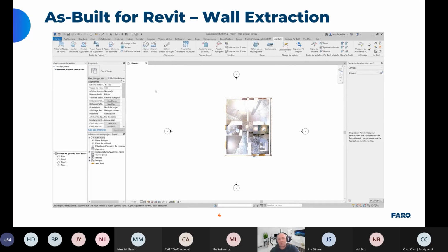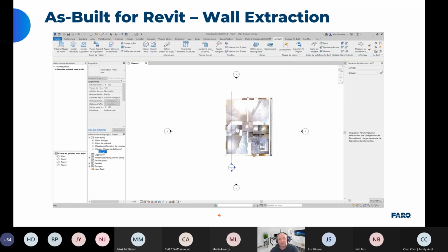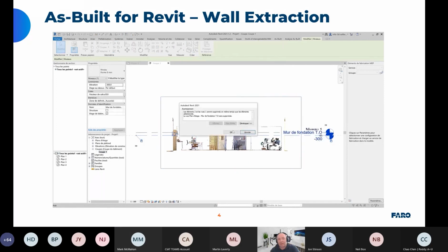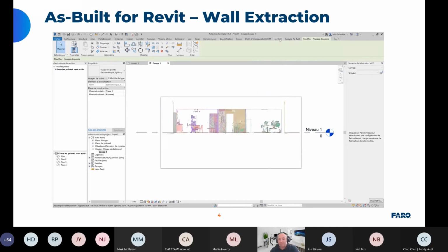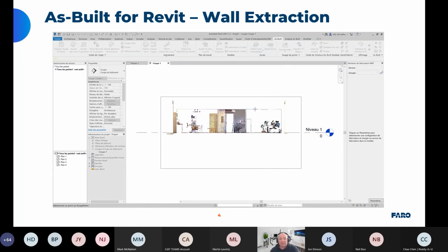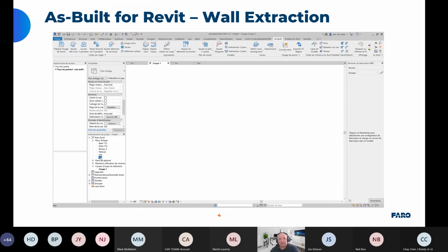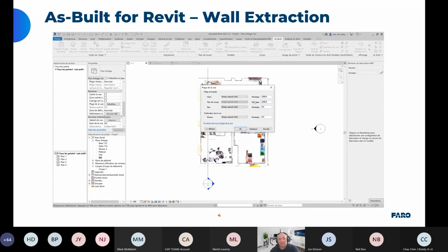After, we just select the views, so we remove the areas of point cloud we do not want, and once it's done, we'll create our levels like a normal Revit project. So it's very easy. We just move the point clouds. We'll see later on that we'll be able to share the coordinates between Scene, Revit, and the final data. So in a few seconds, we prepare our projects.